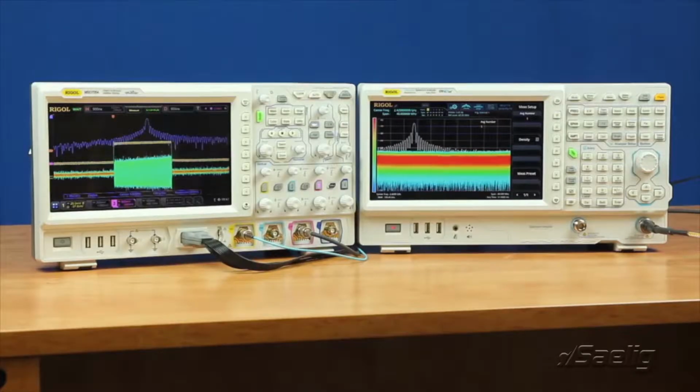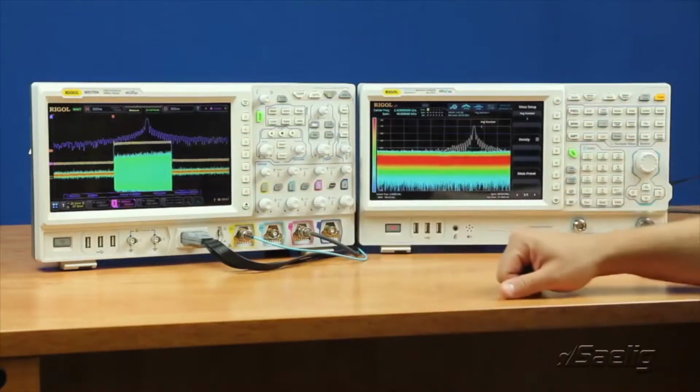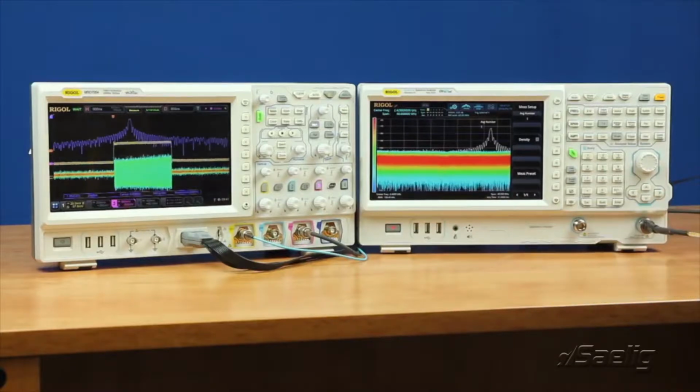One of the advanced ways we can look at a sequence of pulses using the deep memory 7000 series oscilloscope is to use record mode. Here we're still capturing a series of these pulses, and we can see the frequency moving around. We also have different pulse types. Like we talked about, we have some good pulses and some pulses that have gaps in the center. So how do we look at the sequence of events there?